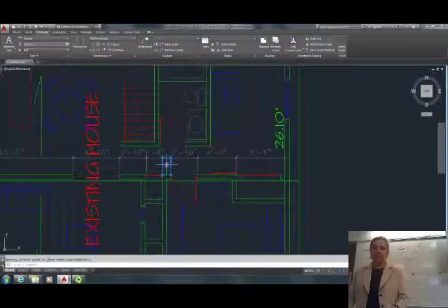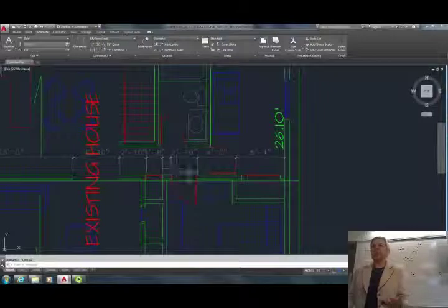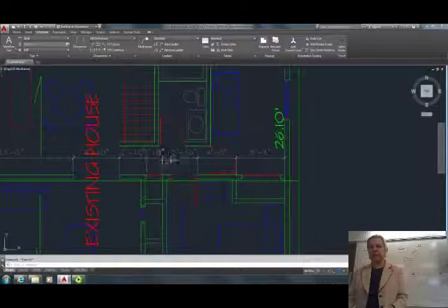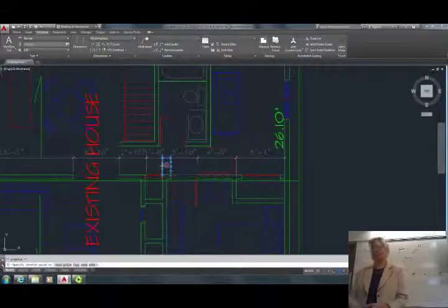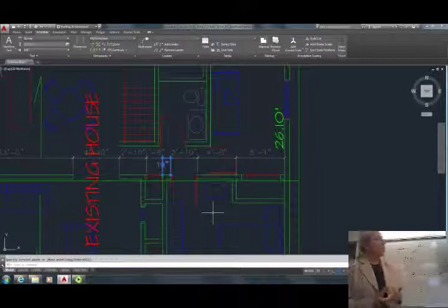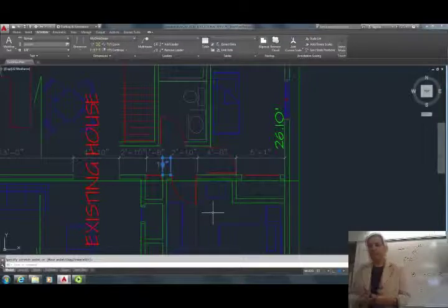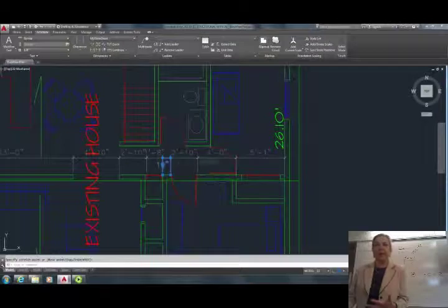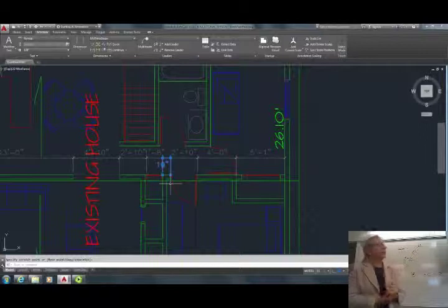The other thing that can happen is the note might be, like you see how extension line sits right on 1 and we actually don't see it. So let's see if we can actually physically move it somewhere where it would not interfere with things. So, sometimes you have to make adjustments to have the dimension if it's required, but not necessarily have it the way you're supposed to have it, because if they all mush together, then the contractor is not going to be able to build it.